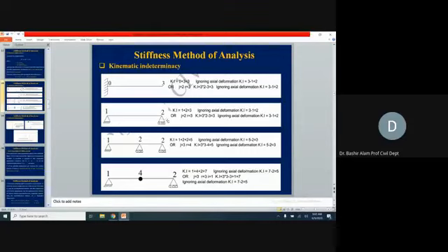At the right support, we have translation in the horizontal direction, and we have a rotation here also. So that is why 2 is written. The total kinematic indeterminacy of this simply supported structure will become 3, which will be coming from 1 plus 2, which you can see here. 1 plus 2 is equal to 3. If we ignore the axial effect, meaning we will be taking away the effect of this one member, this will become 3 minus 1 is equal to 2.